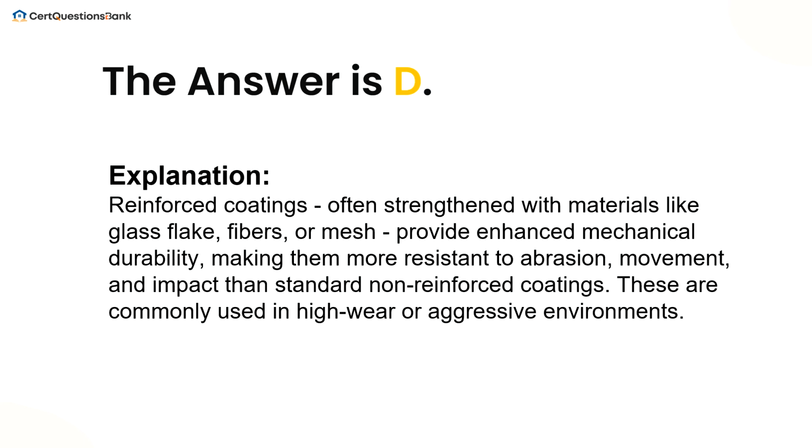Reinforced coatings, often strengthened with materials like glass flake, fibers, or mesh, provide enhanced mechanical durability, making them more resistant to abrasion, movement, and impact than standard non-reinforced coatings. These are commonly used in high-wear or aggressive environments.